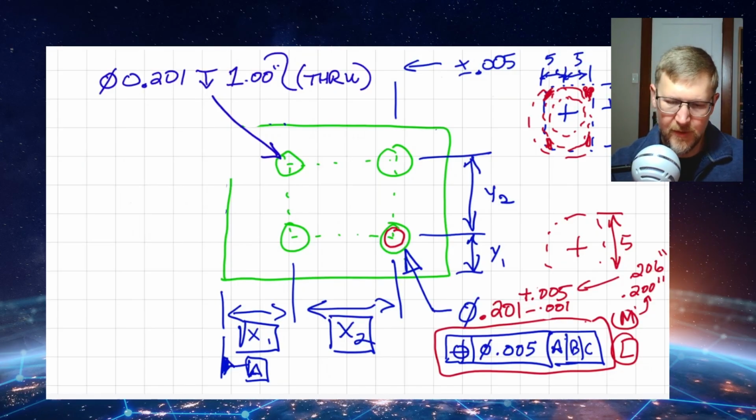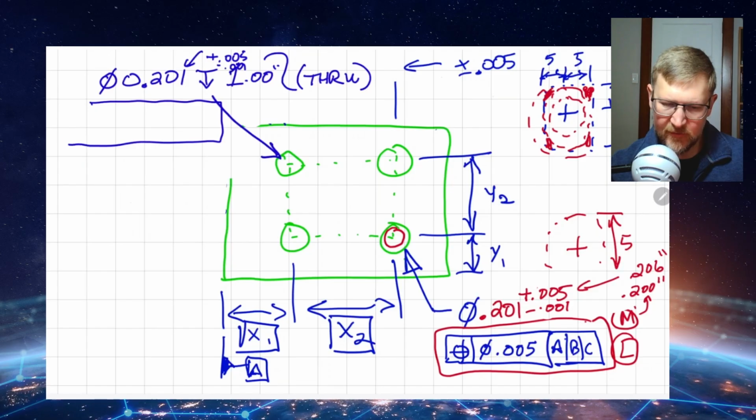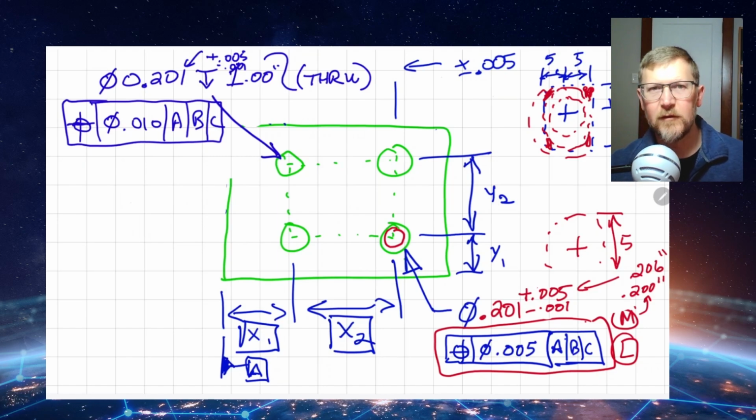Then you're probably going to want some tolerances on this if it's not drawn out somewhere as a standard on your drawing. So again, you may go back to your specs from the NAS standards or other company standards. So this might be a 0.05 minus 0.01. And then below that, if you're doing GD&T, this is where you're going to have your callouts for position, right? You'll have this position callout with some sort of diameter, maybe it's 10 thou, and then the datums it references in order. And so that's what a typical hole callout is like.